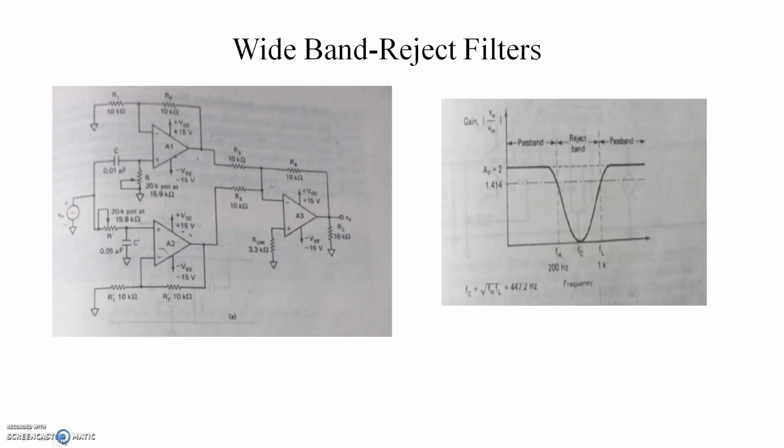In addition, another important thing we have to consider is that the passband gain of both high pass and low pass sections must be equal. And its frequency response is shown in the right side figure.